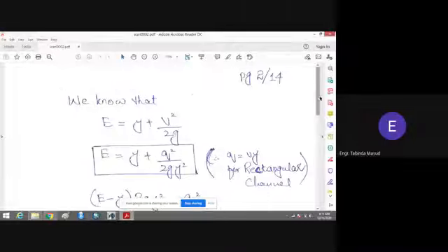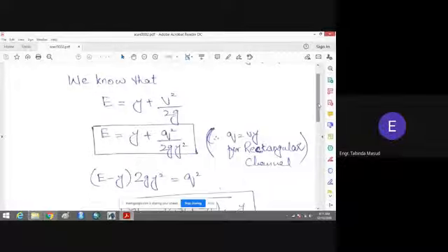Now, in order to develop a discharge curve, we use this equation which we have already discussed in our previous lecture: specific energy head E is equal to y plus v squared divided by 2g. The relationship between this v and the unit discharge is q equals v times y for rectangular channels. So we are going to develop this discharge curve for the rectangular channel.